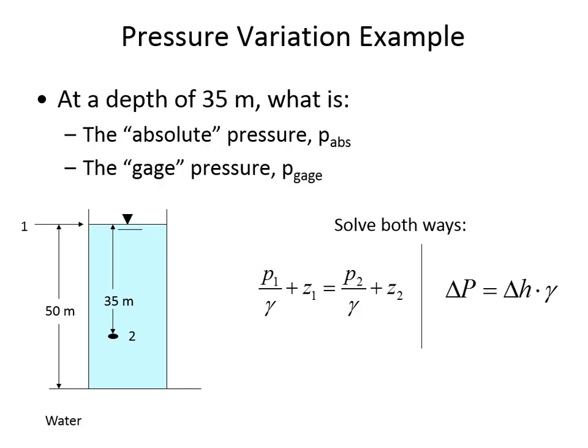All right. So if we know that there's some distance up to the water surface, since we selected location 1 as the water surface, then that would be Z1. And what is the gauge pressure of the air right there? Very good. Remember, the difference between absolute pressure and gauge pressure is that when we talk about gauge pressure, we're saying that it's relative to atmospheric. And so right at the water surface, the pressure at 1 relative to gauge is 0.